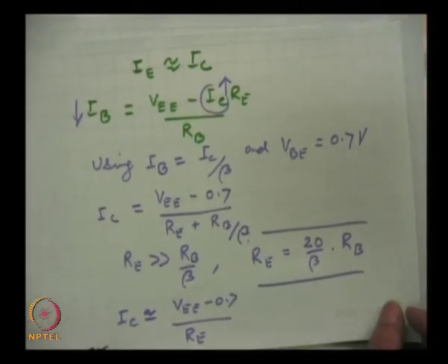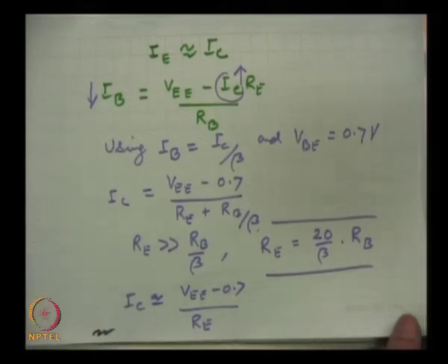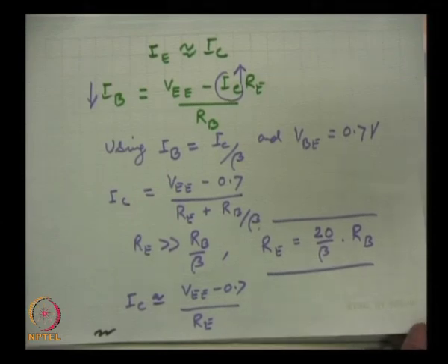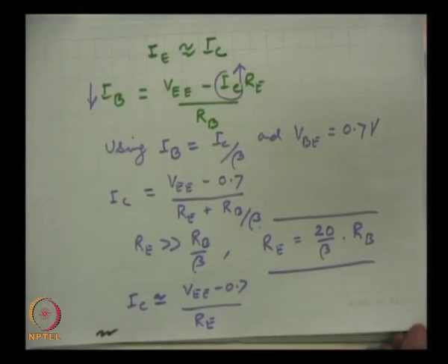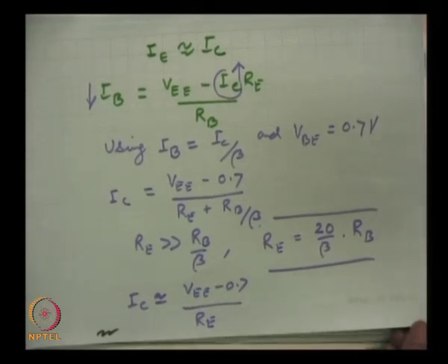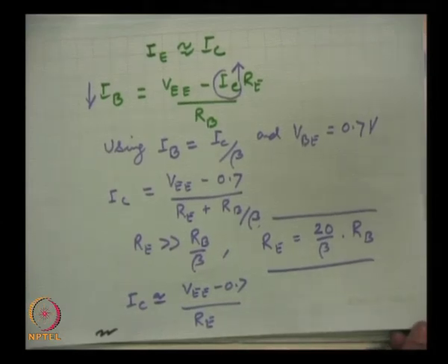So, this shows that it is a highly stable circuit, design is simple, number of resistances used is smaller and high stability. So, this is very widely used biasing scheme for BJT circuits. Now, the only point is that it needs dual power supply. Which is of course easily available, and so when dual power supply is available, we can use this circuit.